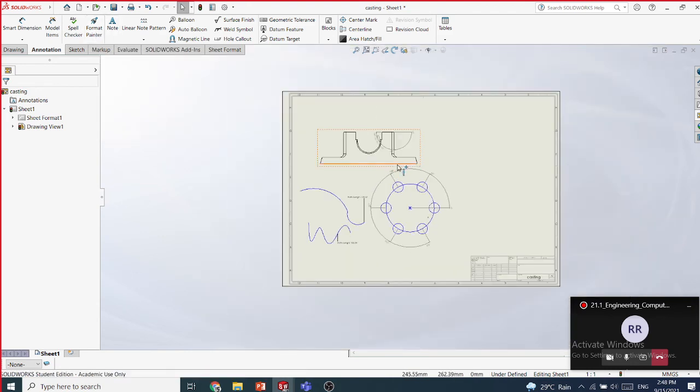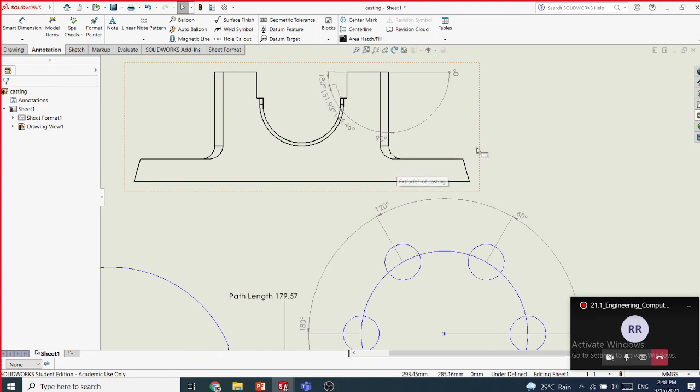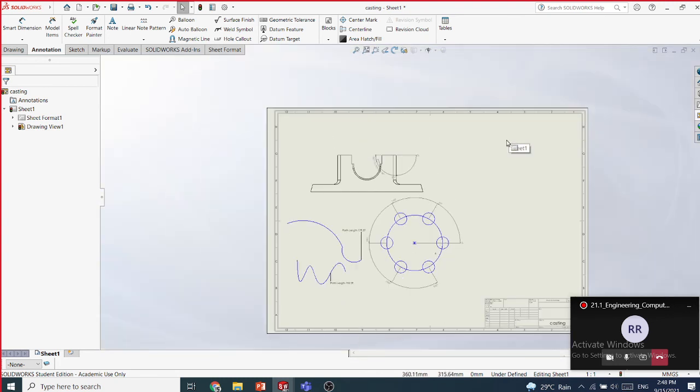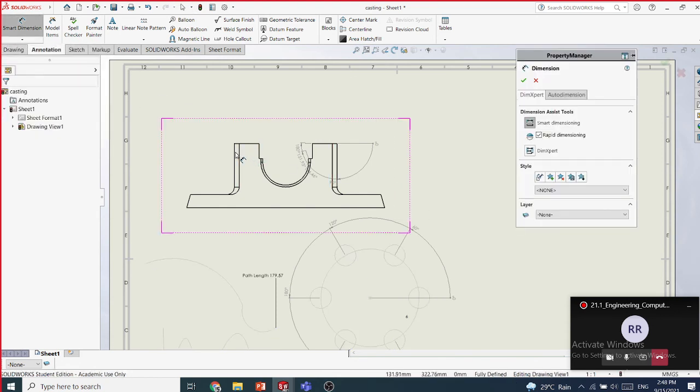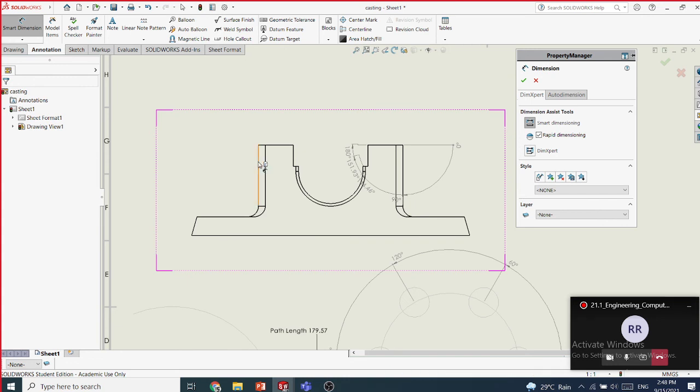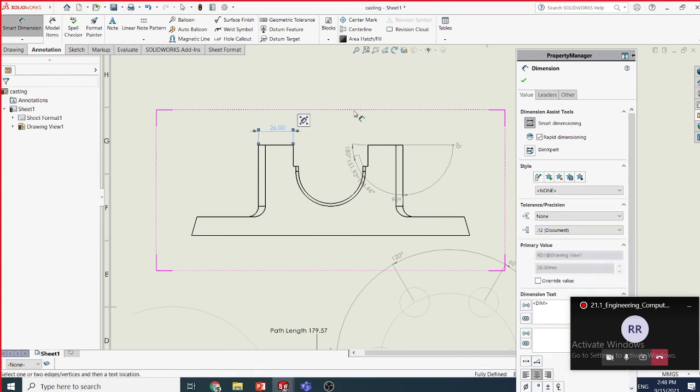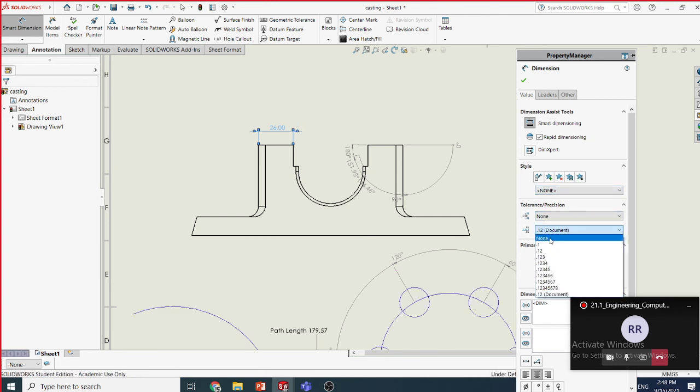So I will show it here also. We'll have a simple example. If you don't create a style, we can do these methods also. So I'll put dimensions as 0 here, decimal place as 0.